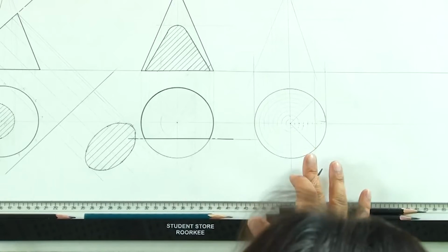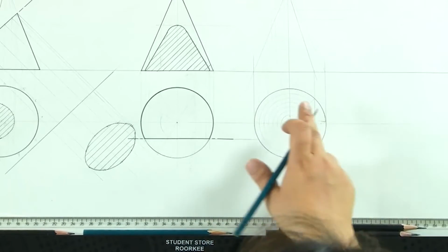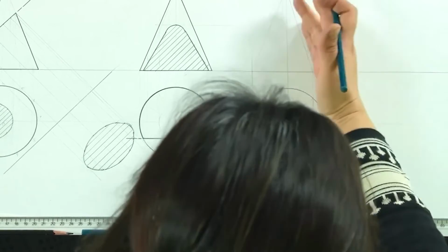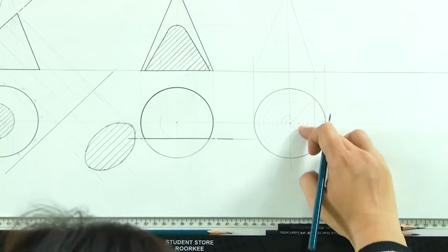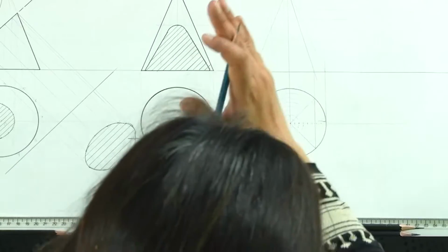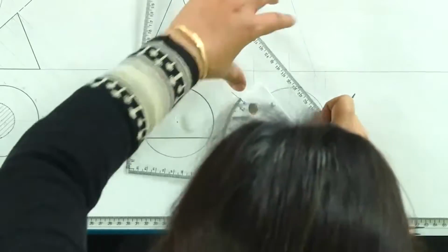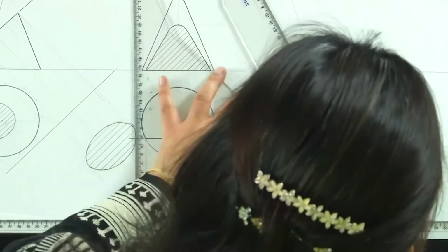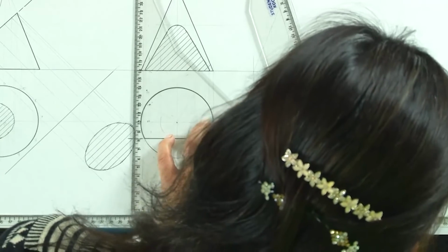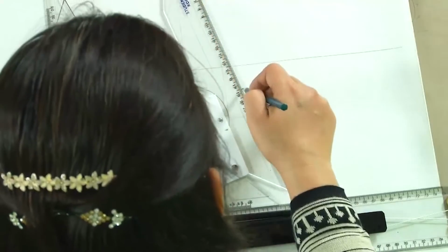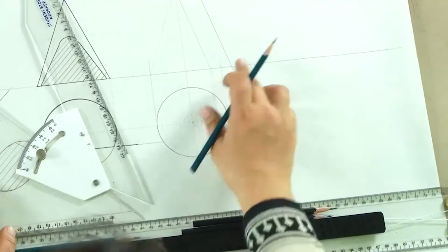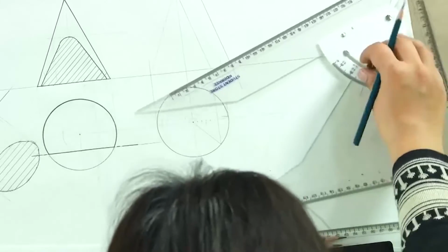So, if I want to now draw the true shape of the section which is going to be parallel to this. Because in the top view we will only be getting to see this triangle, and in the front we will only be getting to see this straight line. So, let us try to draw the true shape of the section here. So, I am fixing it parallel to this section plane again, and I will now take the projections.